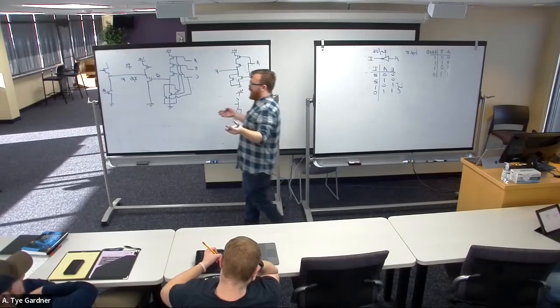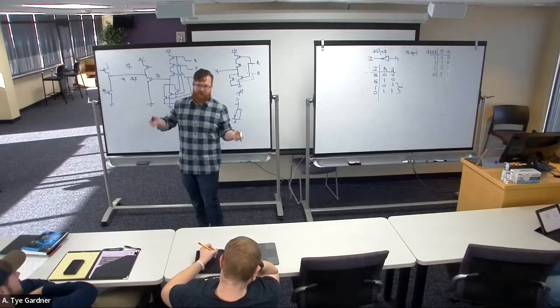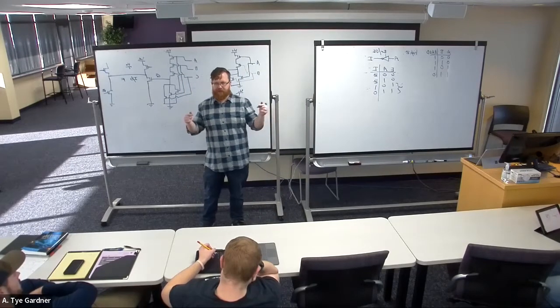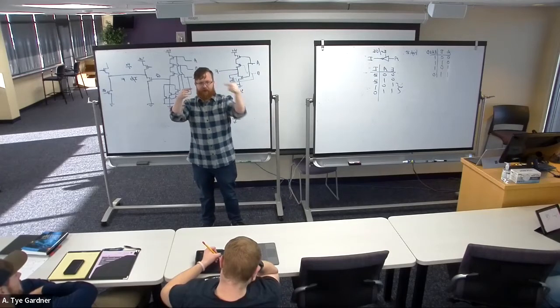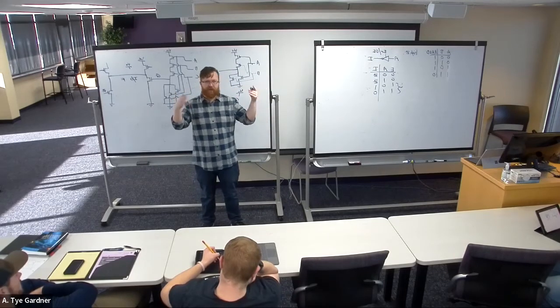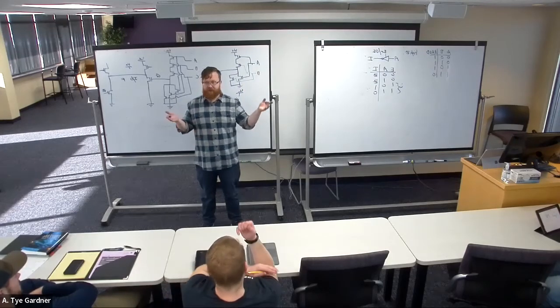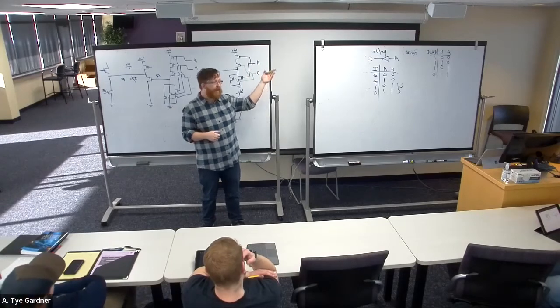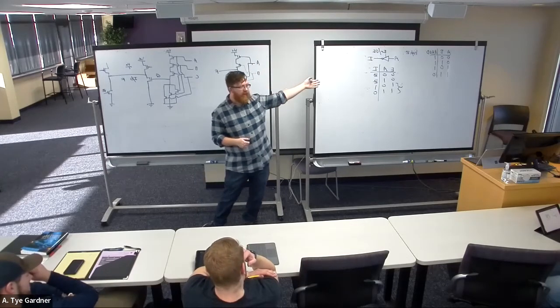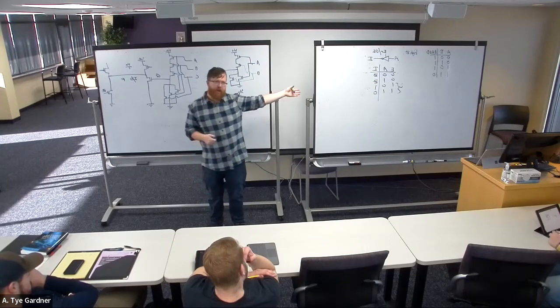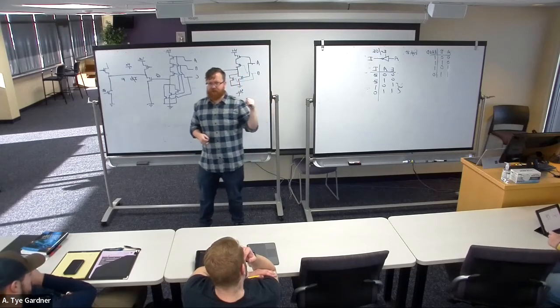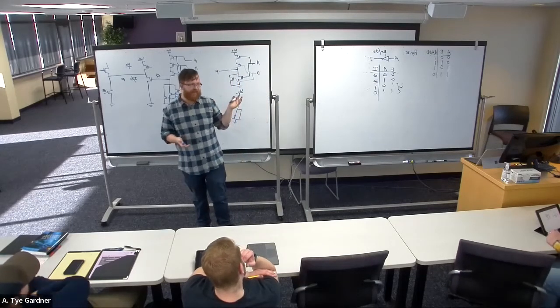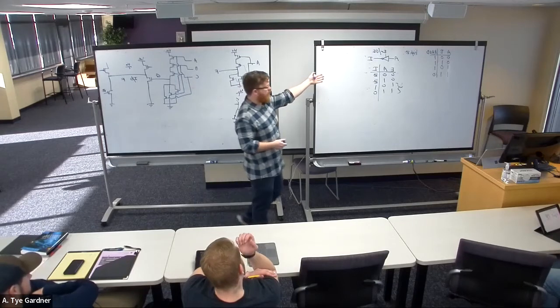In an ideal world, that's infinity, but it's not really infinite, right? Electricity can jump from one wire to another. It can arc. The reason it takes a high voltage in order to arc is because the resistance of air is very high. It's very difficult for electricity to flow through air, but it can. And that's what the high Z is saying, is it could, but only if something went catastrophically wrong, basically. That's what high Z means. This is high impedance.